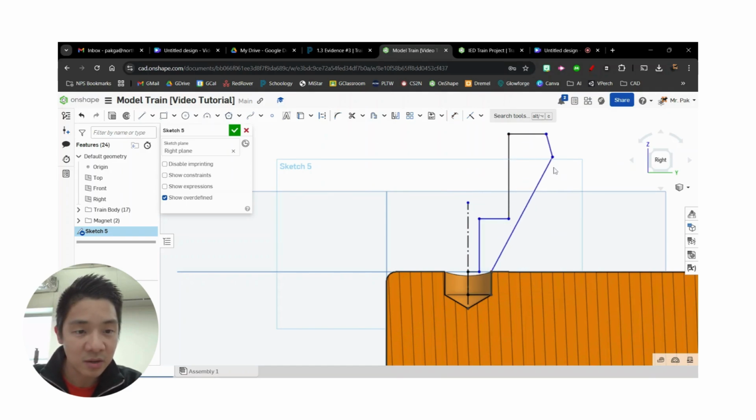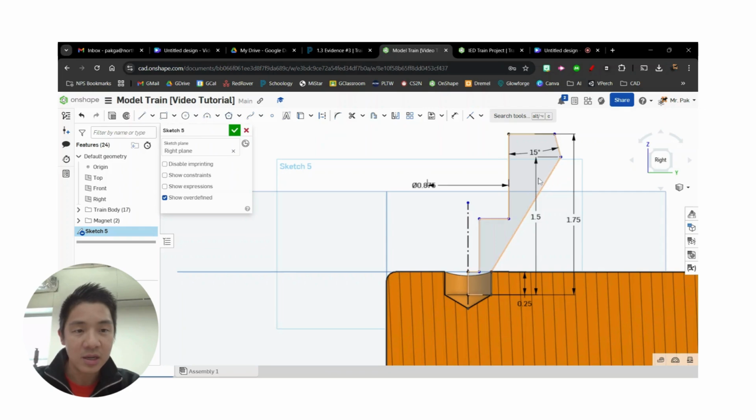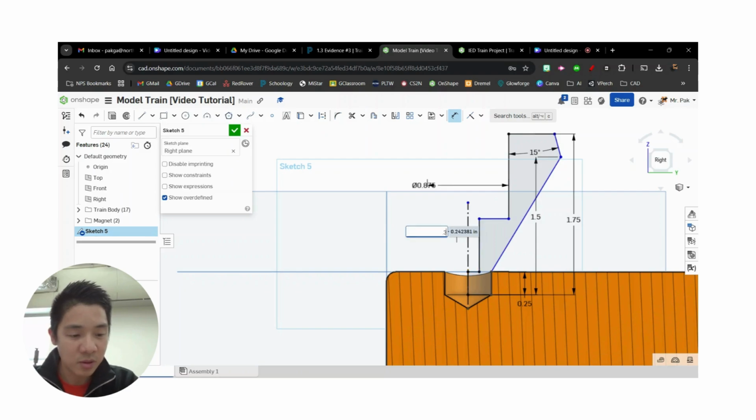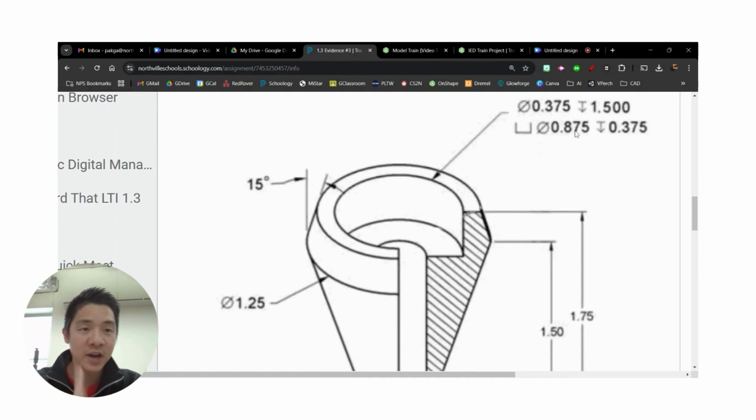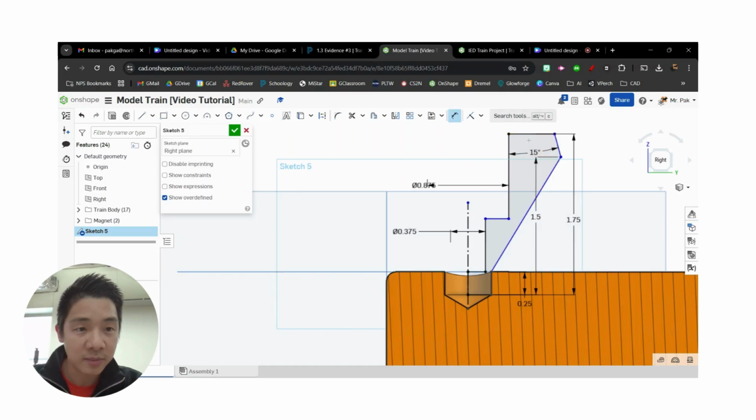Okay, I'll fix that right now. Just go ahead and drag this out. So that goes actually a little further out than I thought. And then the hole itself from here to here was 0.375. That's what I saw on this measurement right there. Okay, so that's going 1.5 deep, 0.375 for the counterbore. So let's do the 0.375 for the counterbore first. This is dimensioning from here to here. This was 0.375. And then for the entire hole, from here to here, this measurement was the 1.5, and that looks correct already.